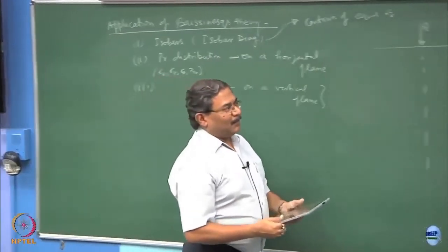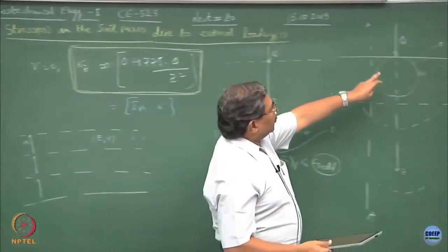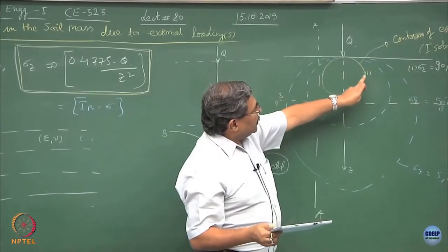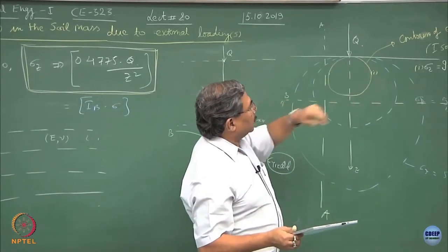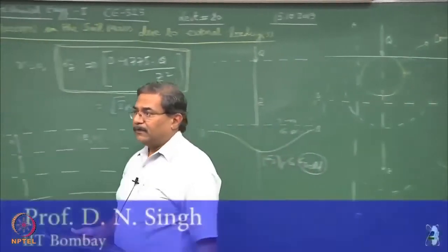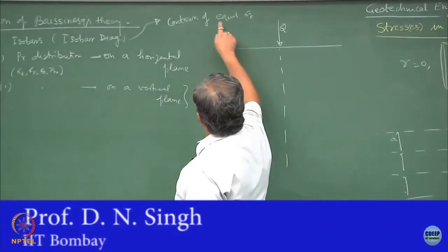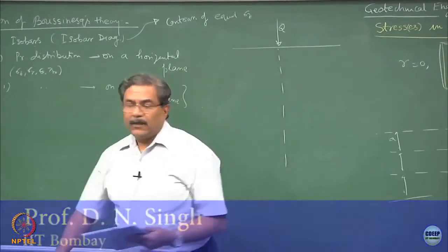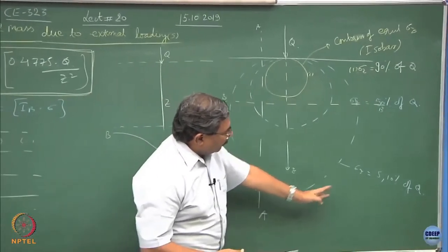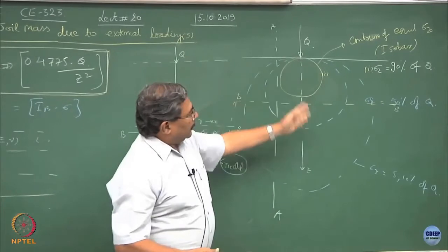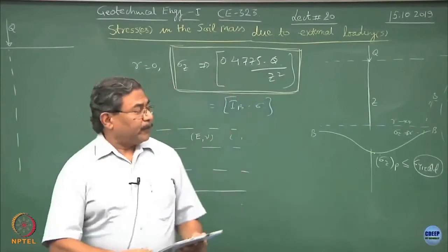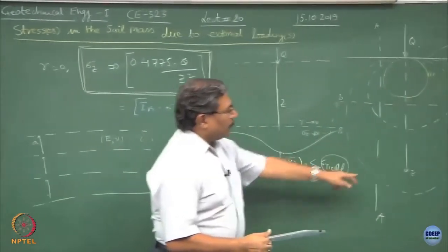Not the inside part, these are the contours of the points, he was discussing each and every point on this surface is going to be of 90% Q value. So, that is why we call them contours of equal sigma z's, fine. So, as you come deeper, the pressure intensity is decreasing, this becomes only 5 to 10% of the Q value, and you can use this expression which I had written over here to compute the state of stress, and you can plot it over here.